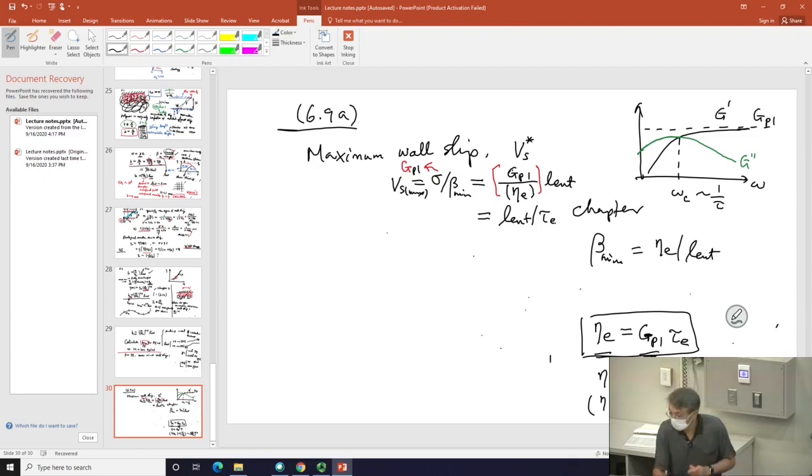In other words, if you don't have monodispersity, this does not hold. Number two, since nothing is ever purely monodispersed, 1.1, 1.2 polydispersity index is even good, fine enough. And there, it's always safe. You had a good question. It's always safe to think that this M is weight average molecular weight.